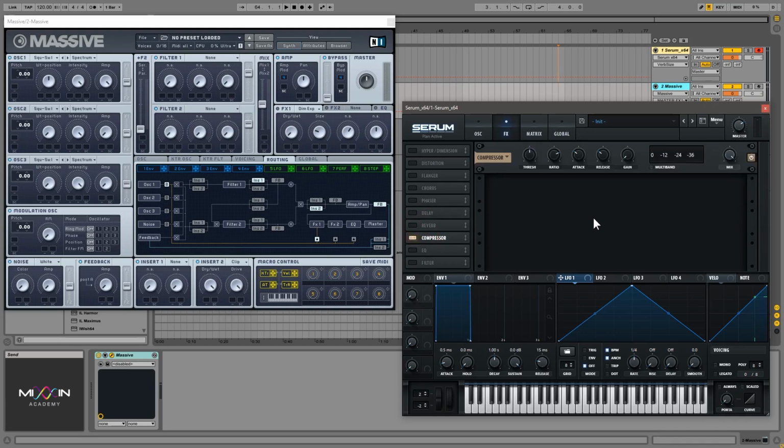We have a compressor next, and the compressor is a dynamic effect. It affects the amplitude of the sound. So how every compressor works is we determine the threshold, we set a threshold for the sound, and if the sound that comes into the compressor surpasses this threshold, it will be attenuated in this ratio of, let's say, 4:1. So whatever passes the threshold of minus 15 dB, if the sound is louder than minus 15 dB in digital full scale, it will be attenuated 4 times.